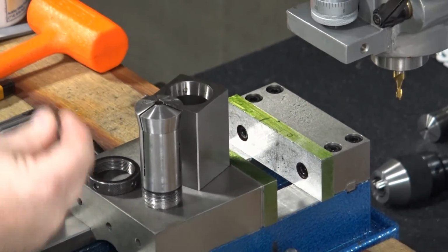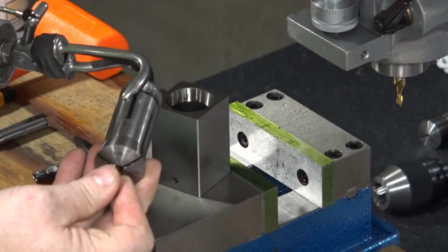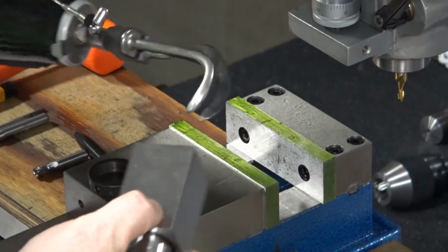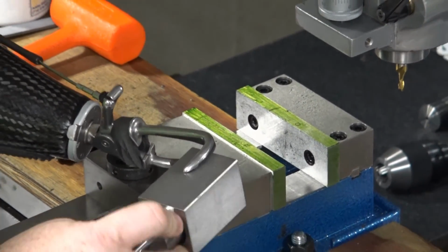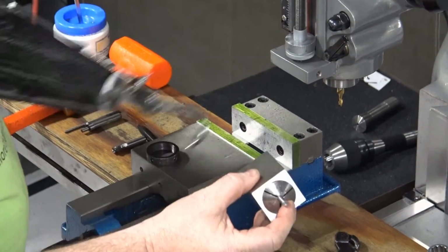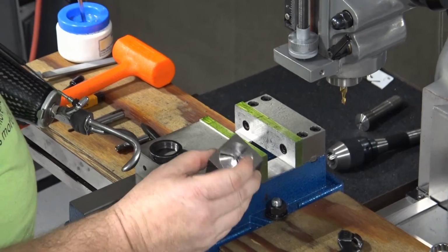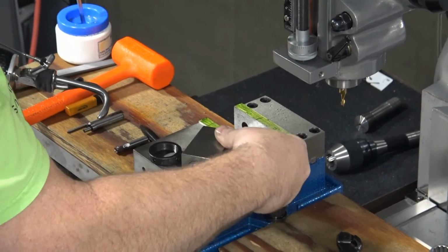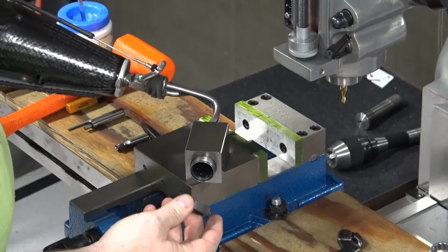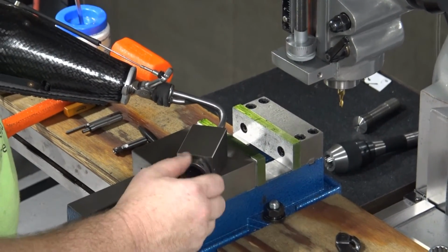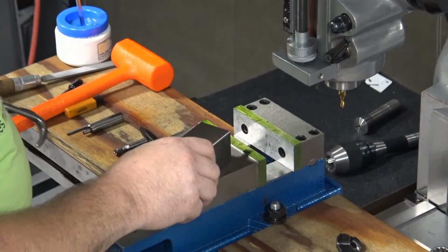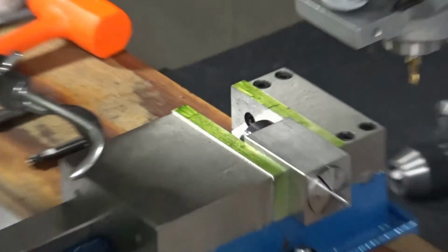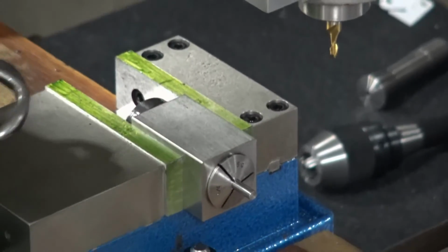So 930 thousandths. We're going to go back to our 5C collets and this collet block. The first thing that we need to determine is how much I want to stick out so that when I machine the flat on that piston, I'm not machining into Mr. Bryan's collets, right? These have been machined into a few times. That doesn't mean we want to continue to do that. We're going to take the threaded collar and thread it up on the back side. And then we're going to do our math. You should have that math already written down in your notes somewhere. It's 930 thousandths minus 310, which gives us 620.